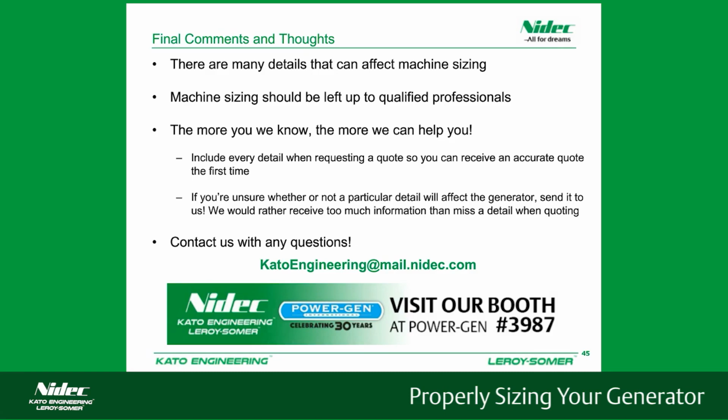I would say whatever your codes require. For instance, NFPA 110 and other codes have a requirement for the sizing of the generator compared with the maximum continuous load. But apart from that, none, because we size our generators to deliver the full load continuously 24/7.